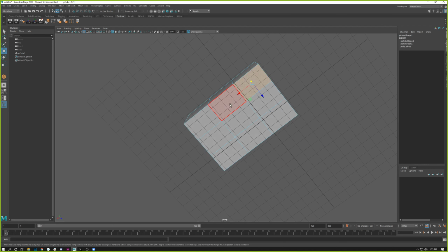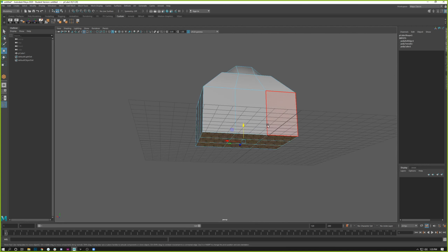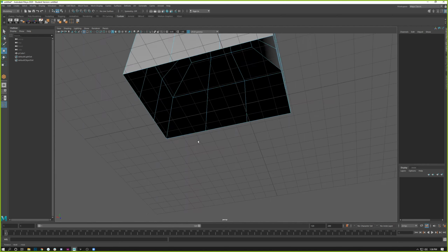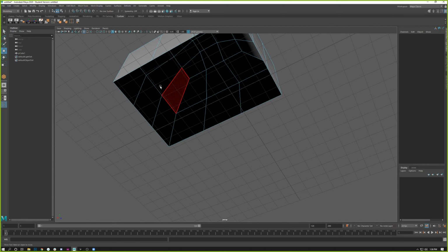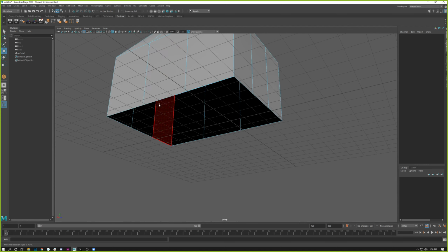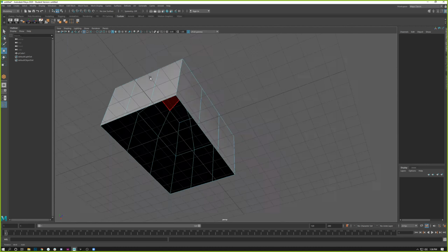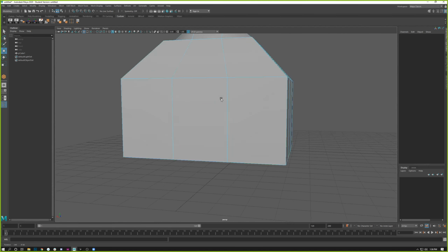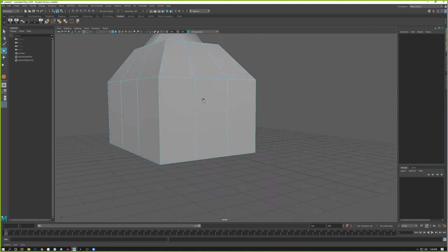Now, faces, you can also delete faces, and we actually did this in the first lecture series. You can delete faces as well, and what this tends to do is make things hollow. In fact, we did this for the top of the temple. So if I come in here and straight up just delete these, we can make, let's just, I don't know, a house. You can see it's completely paper thin, and the inside is, for the most part, pitch black. This is Maya's way of denoting what the inside of an object is.